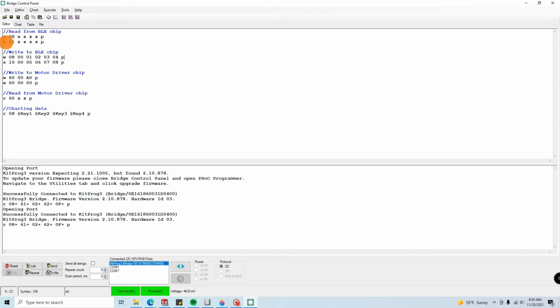You can also do it using a standard start condition, but then you have to use the full 8-bit address and declare the correct read-write bit at the end of it, like I talked about earlier.